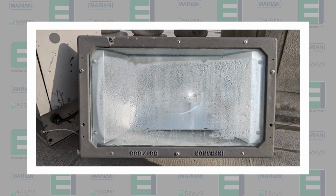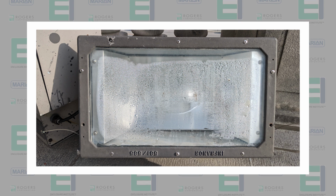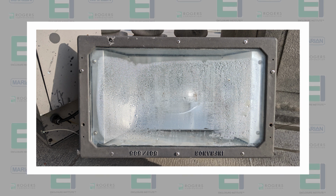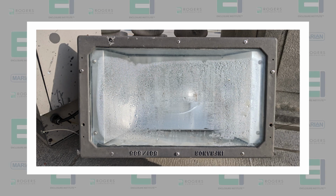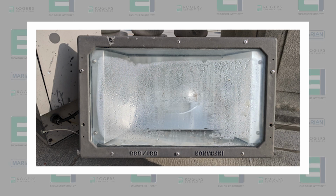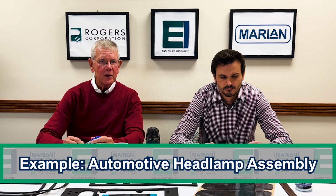A proper vent will also help control the buildup of moisture and condensation within the device. Trapped moisture can corrode the electronic connections and circuits. If the device has visual components such as a lens or a glass cover, the buildup in moisture will cause fogging. By allowing air to flow into and out of the device, the humidity level can be controlled, minimizing these sources of failures. For example, let's talk about an automotive headlamp assembly.